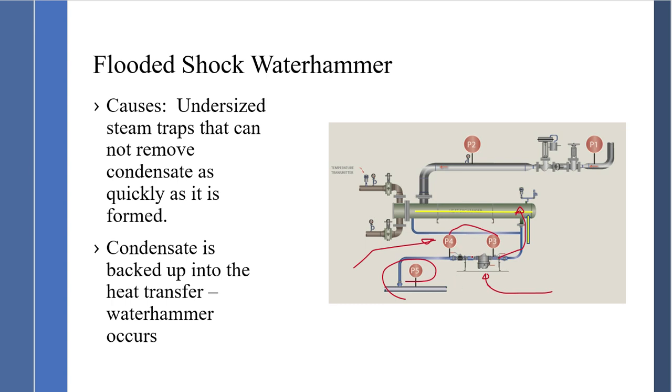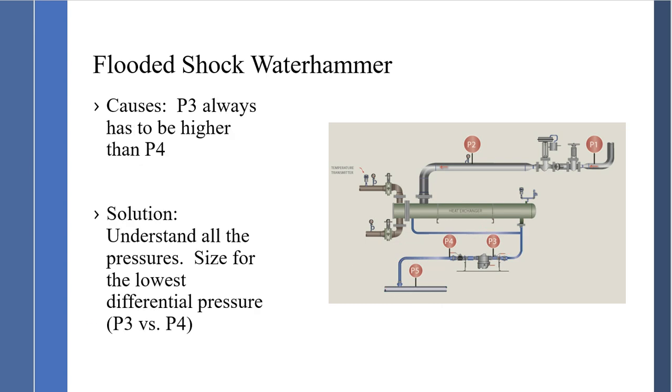The thing with sizing steam traps, take the time to understand what the differential pressures are, P3, P4. Always have a qualified vendor supporting you on the sizing application, and know the dynamics of your condensate return system. That resolves a lot of the issues with what we call flooded conditions.